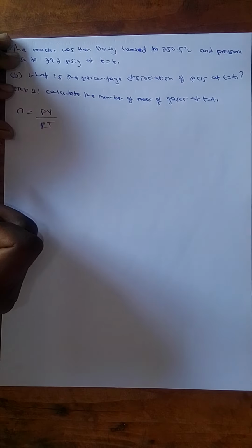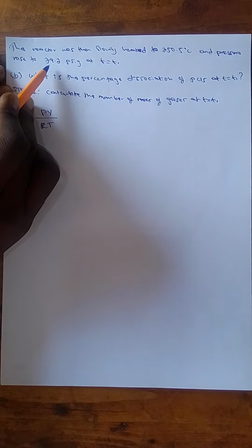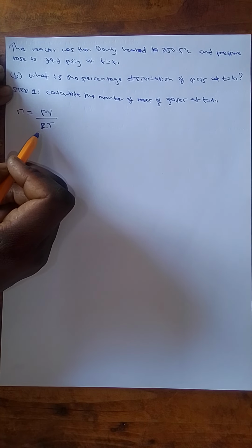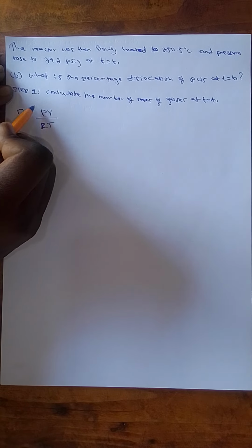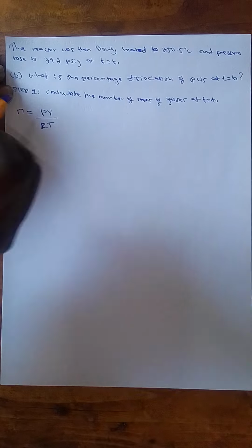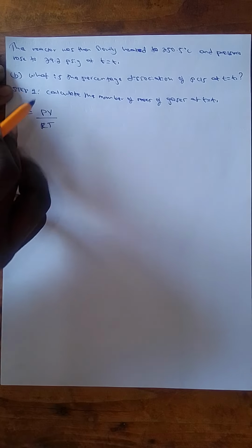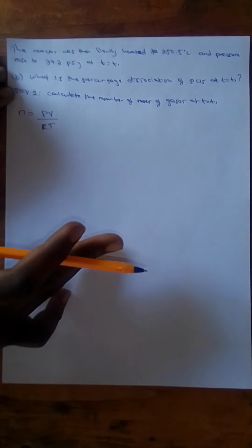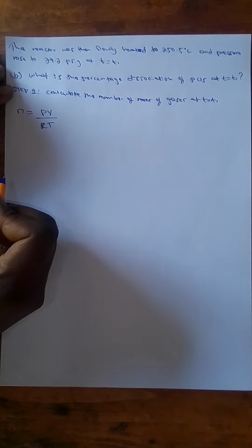We have the volume, we have the pressure because we know the gauge pressure, and we are given the atmospheric pressure, and we also have the R and the temperature. So it shouldn't really be that difficult. However, it's important that we sort out the pressure first. Firstly, we need to find the absolute pressure, and then we need to convert the absolute pressure from PSI into kilopascals. So that is actually something we needed to do.